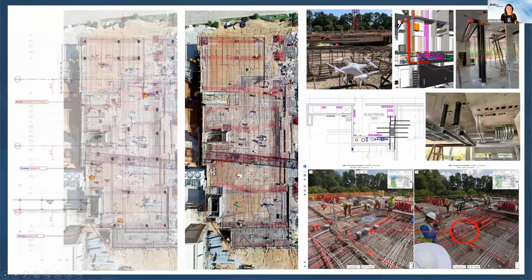Are those a compilation of photos that are put together from the drone, or is it like one giant photo? Do you know? So we've taken both approaches. Some are an ortho mosaic where it's a composite of multiple images, but sometimes you'll get a little bit of skew with that. So it's better if you can do just one complete overall image.